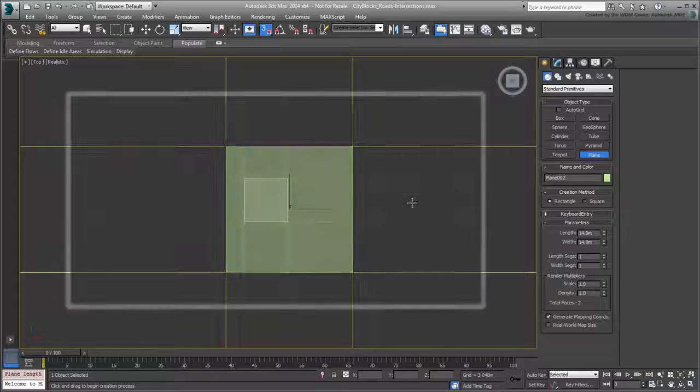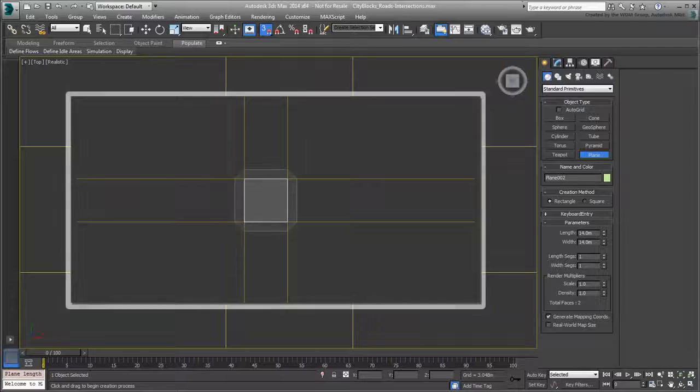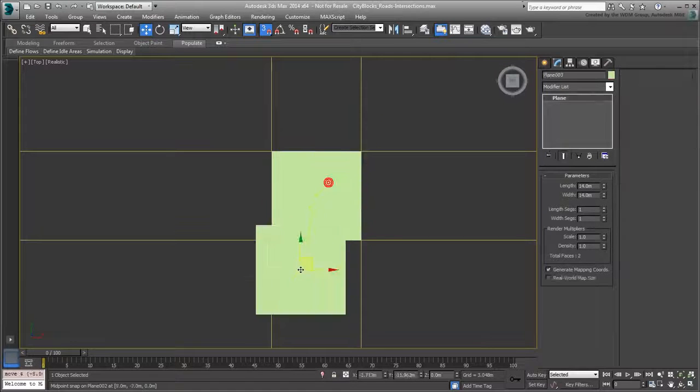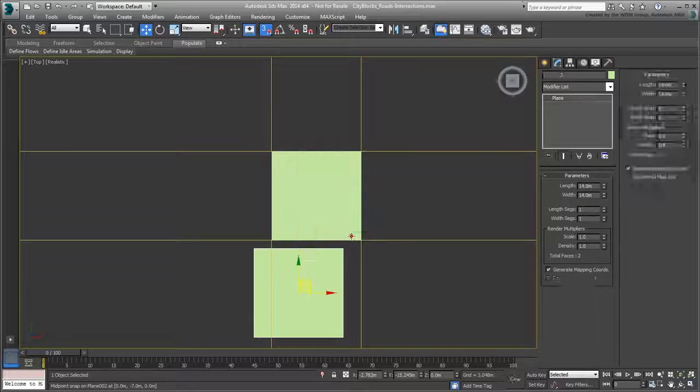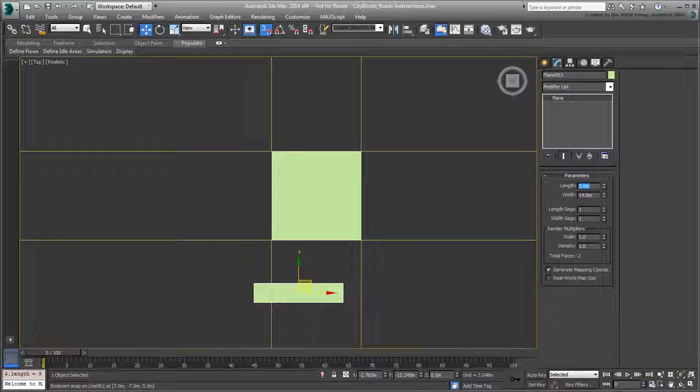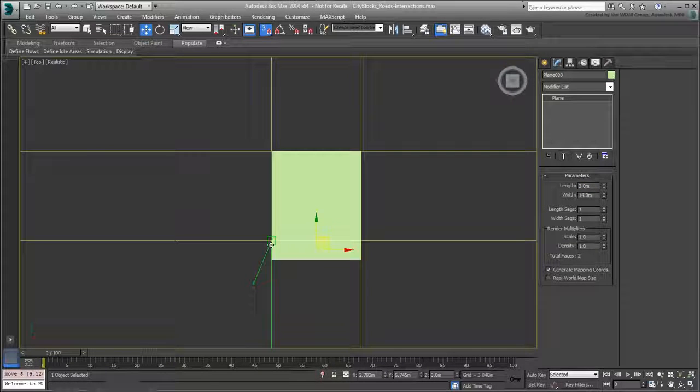As explained earlier, you need to expand this to favor the curved or chamfered lots and sidewalks. Copy the intersection lower and change the length to 3 meters. In this case, 3 meters represent the chamfer value you will use for the sidewalks later. Using endpoint snaps, relocate that strip of asphalt right below the intersection.